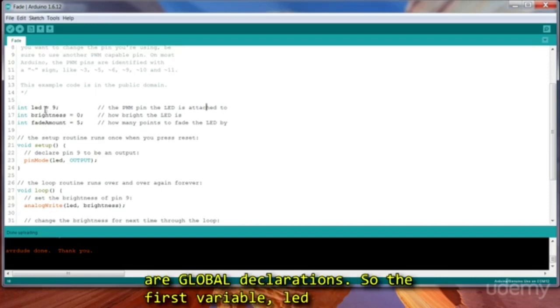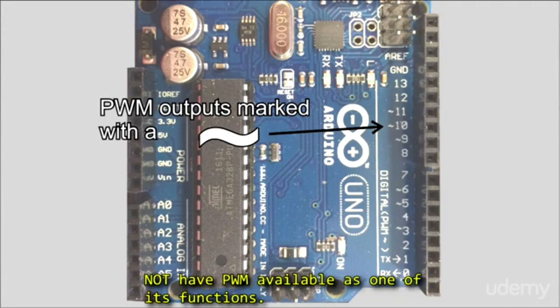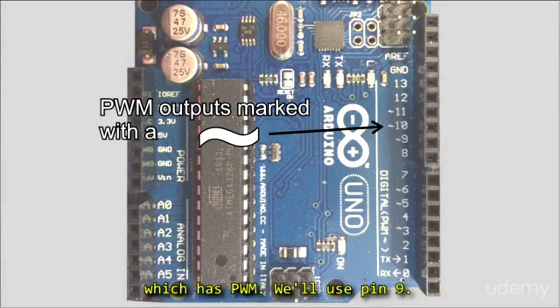So the first variable, LED in all lowercase, is actually the pin number the LED is going to be connected to. Now notice that the onboard LED is connected to pin 13, and pin 13 does not have PWM available as one of its functions. So we have to use a different pin. One of those pins which has PWM, we'll use pin 9.